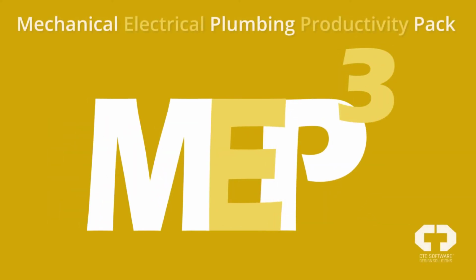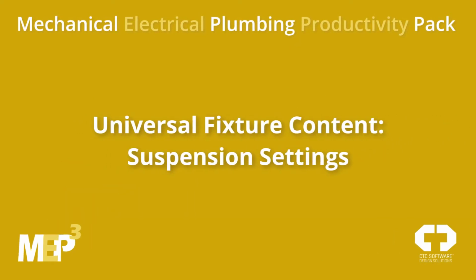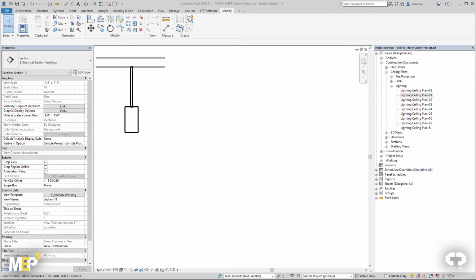This is a tutorial on the suspension settings for CTC's Electrical Productivity Pack's universal lighting content. In this video, we'll see how many of the EPP's universal lighting families can be suspended from the ceiling with or without a stem, and how the fixture's recess settings affect suspension length. In this example, we will be looking at the round ceiling floor fixture.